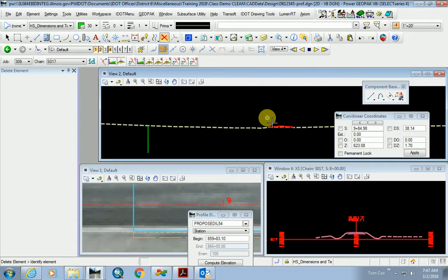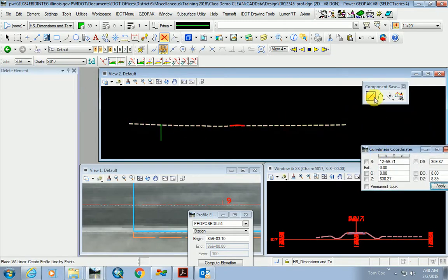It roughly says something to the effect of you need to use a minimum grade of, I think it's 0.75, but you'd want to check that. And you need to go back so far, which is roughly like the middle of the ditch, or I believe it also gives you a distance. Now, sometimes you have certain criteria. You have existing conditions, and sometimes you just can't quite get there. But generally speaking, when you're designing side roads, try to make sure you're not draining water onto the mainline pavement.